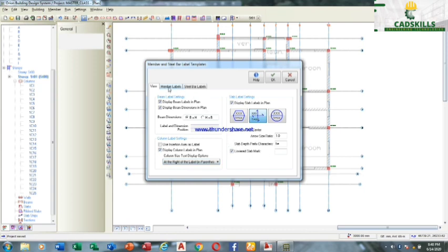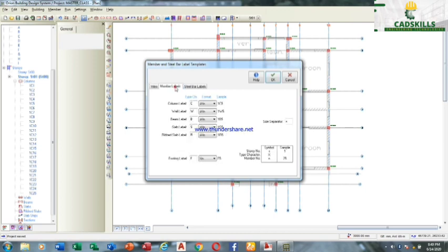Okay, it's going to be showing this, meaning height, depth in your slab. Look at it. It will show you what depth you use. This is how you're going to display it. It will write slab numbering here. It will write H150, H175, meaning the depth of your slab is 150 or 175, as the case may be. If you don't want it to use H as initial, you remove it, put what you want it to use. That's what it's going to display for you. Alright? Okay. Member label. Okay, look at it.